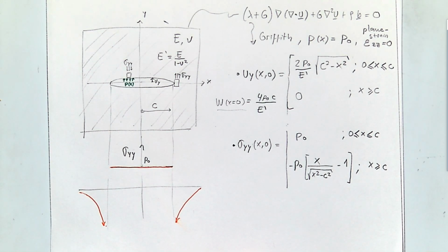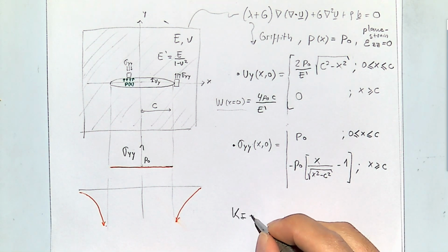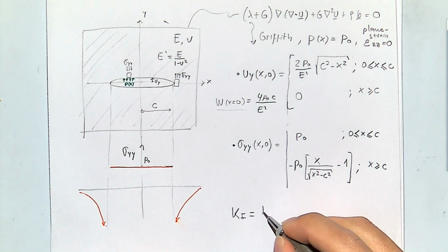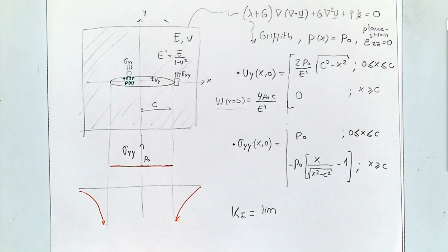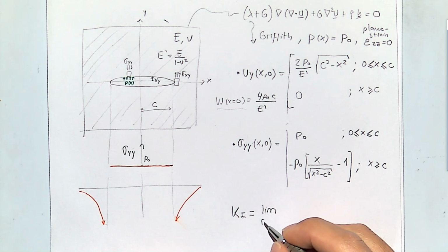So we wouldn't be able to capture fracture propagation with this tensile strength criterion that we have seen before. So instead of that, what Griffith came up with is now what we were talking about before, this definition of a stress intensity factor that is defined as a limit.